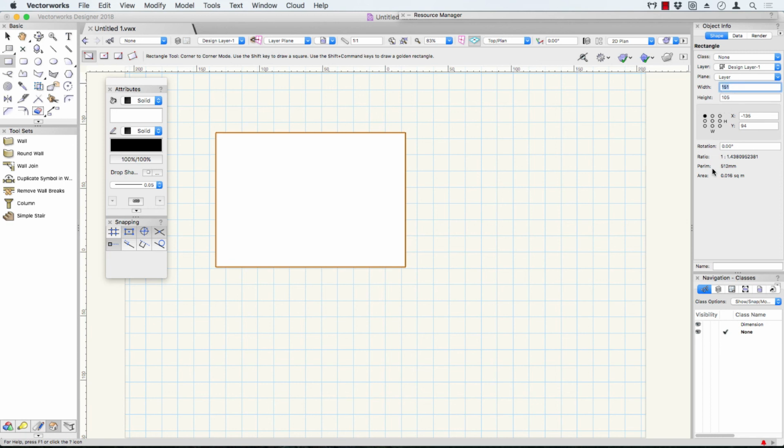I'd like you to change the width to 2 inches or 50 millimeters and then hit the Tab key. One of the things you may have noticed is that one edge of the rectangle remained the same and the rest of it came in from the right. When I hit the Tab key, it highlighted the whole of the next field. You don't have to click and drag your cursor across that. So this is also 2 inches or 50 millimeters.